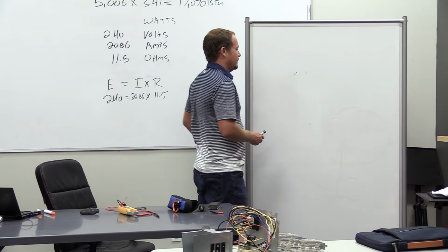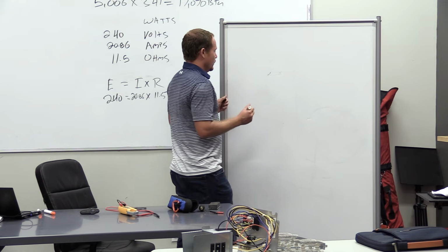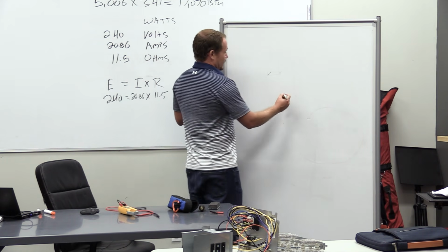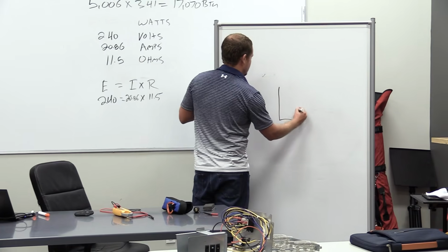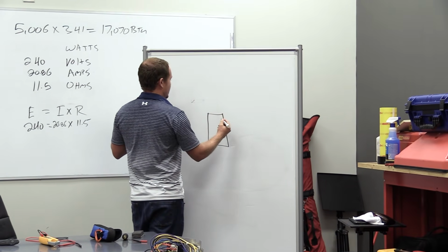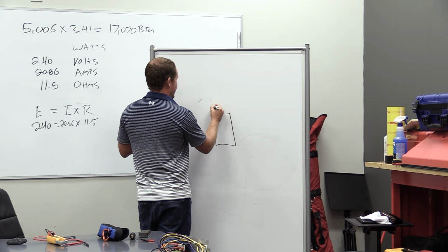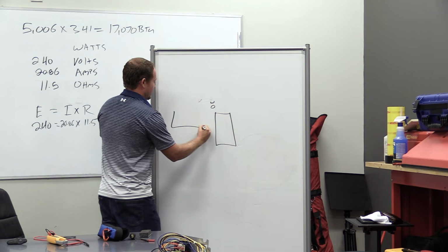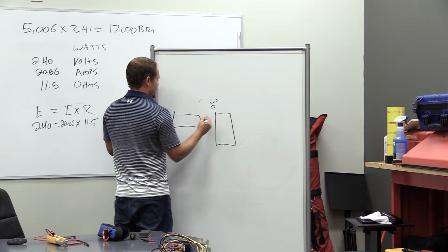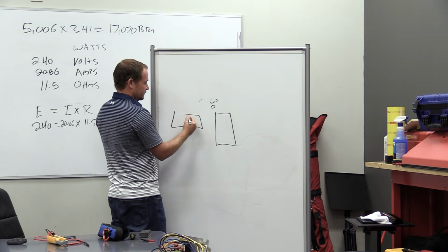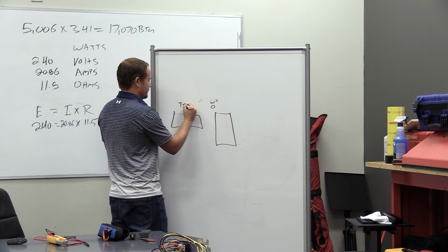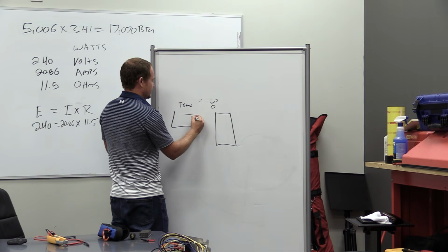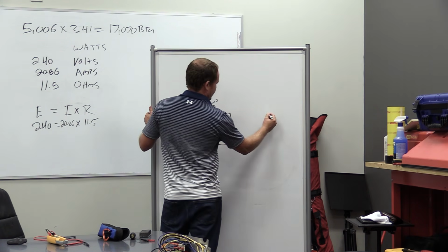Anyway, all right, I can't get this tape off. So we're going to draw it: the air handler is going to be in the center. Can you take that tape off? No. So the air handler is going to have a W terminal here. Our thermostat's going to be here. We're only going to focus on, well, we'll do a W2. We're only going to focus on this circuit. This is our T-stat. W2, and then our defrost board.